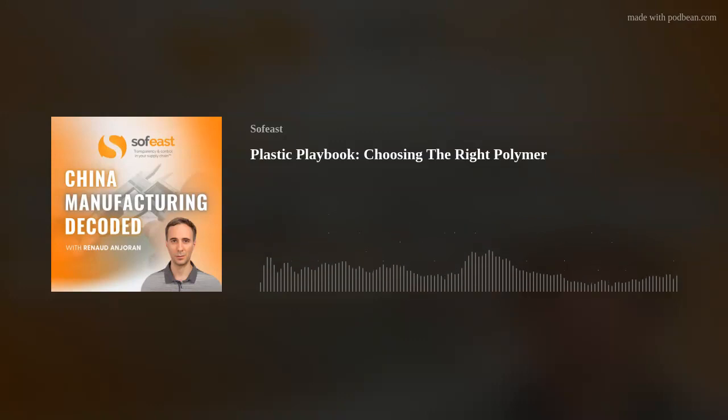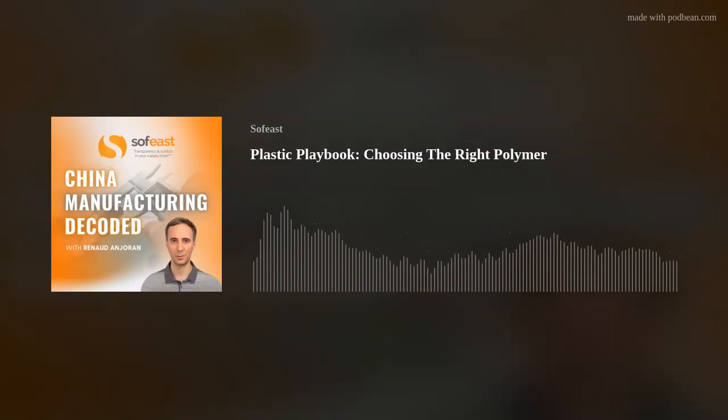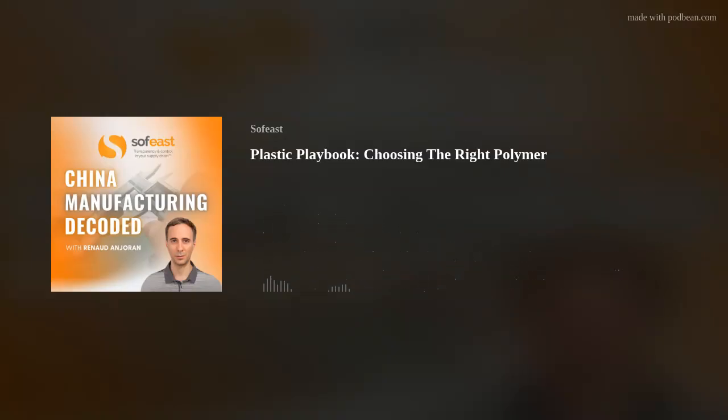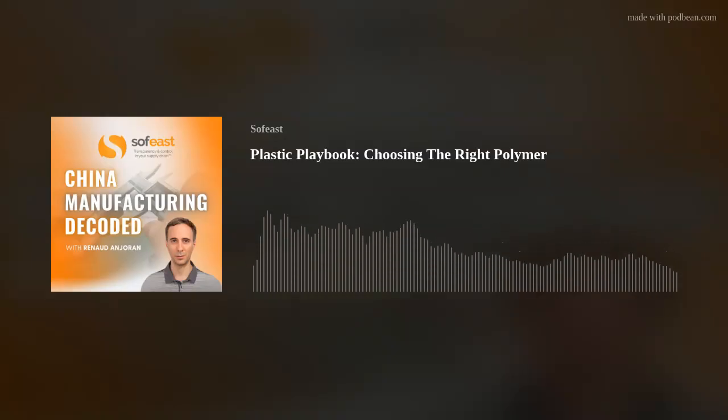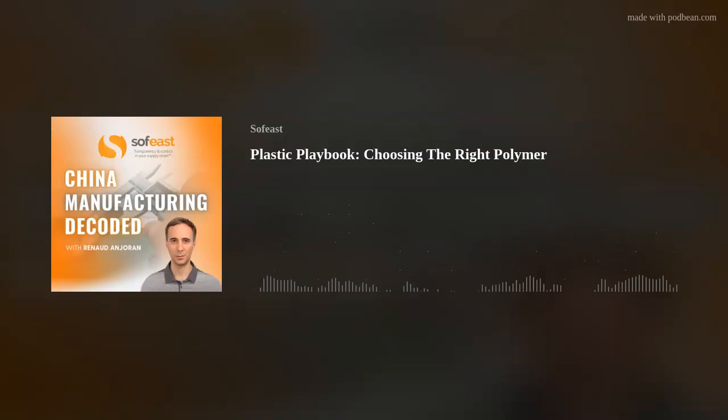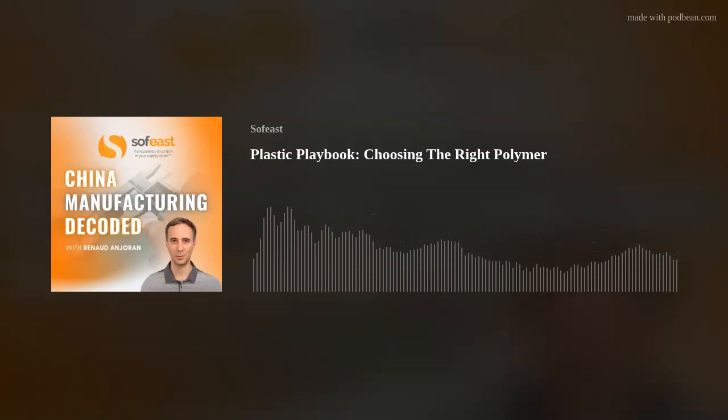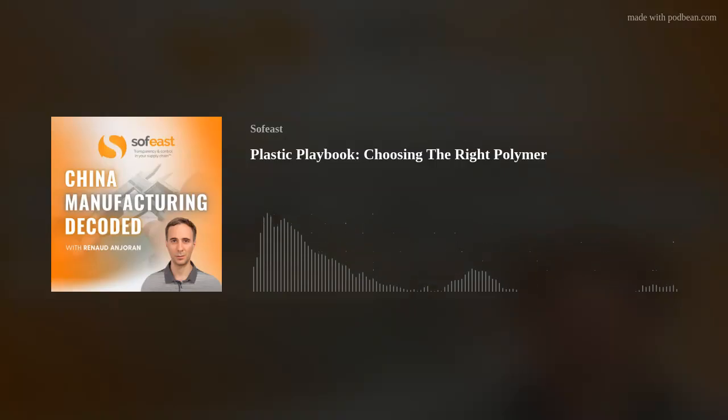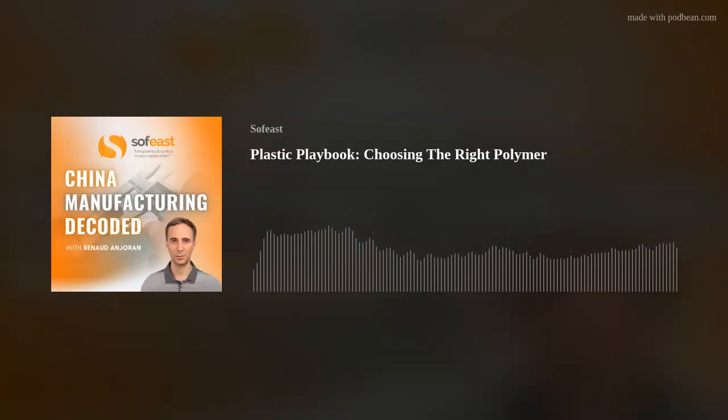So this is where you need to look at the selection of polymer you're using in order to work out what the end result would be if there's a failure. Now, one of the causes of failure is moisture absorbency in nylon, which could mean that the 2 parts, 3 parts come apart and everything falls apart. So some of the things that nylon could be used on, I've already touched on gears, which is a great application for nylon, bearings as well, other automotive products, and general mechanical products. You'd be surprised how many components are made out of nylon, which is good.